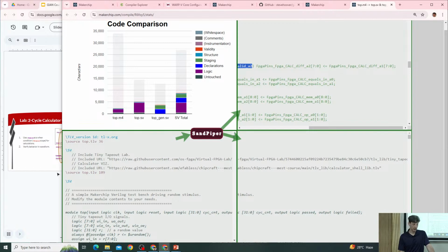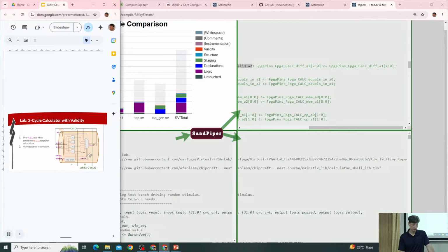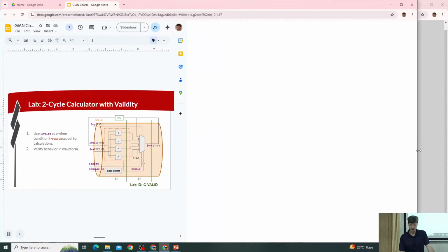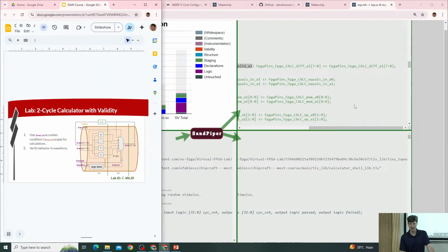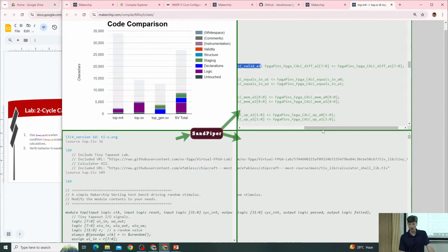Okay, so we do have a clock. We do have flip-flops now because we've gated these expressions, and these expressions produce values that do go through flip-flops. So each of these flip-flops will have a gated clock now. And it's all the same gated clock signal because it's the same pipe stage. So that's why we just have the one clock signal now. And we see that applied to, for example, this diff signal.